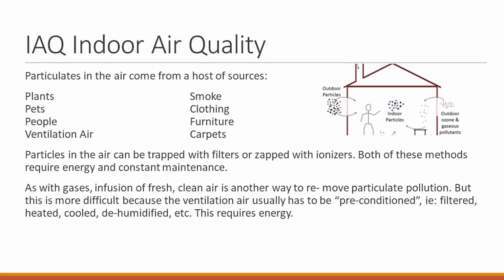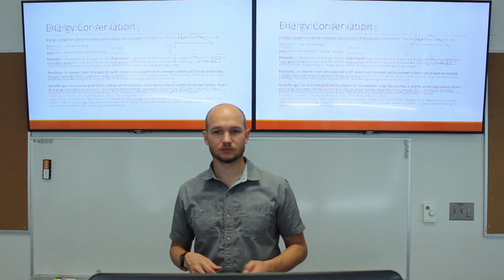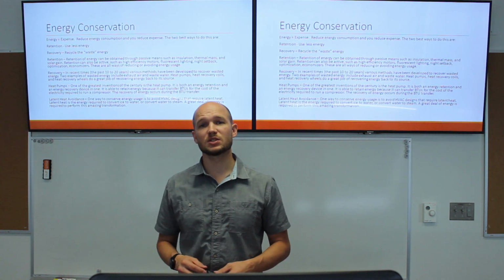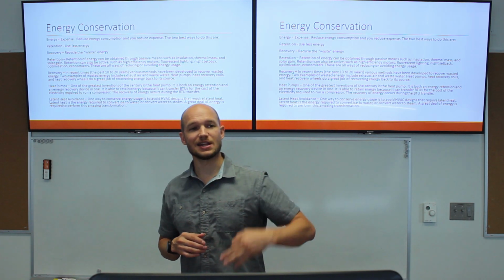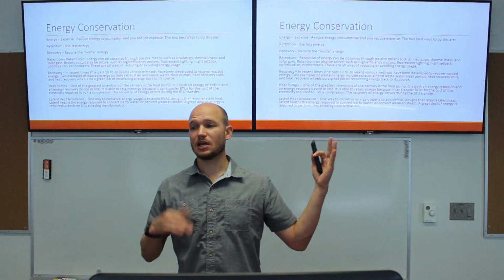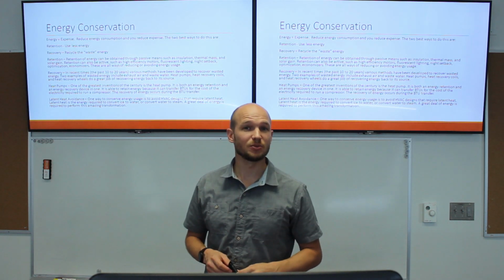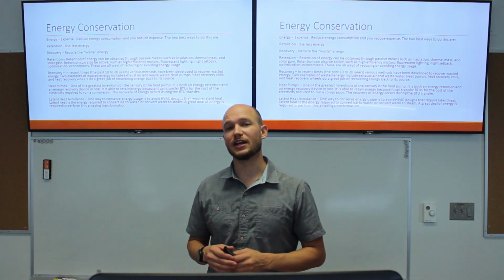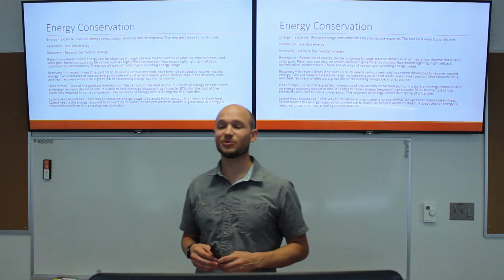So we talked about this already, but particles in the air can cause issues. So energy conservation, we can put in these systems and we can bring this outdoor air in, but what do you do when it's 98 degrees out, humid, and you're putting a building at 72 degrees with 53% humidity? You gotta constantly cool that air, and if you keep doing that over and over and over, your electric bill is going to be pretty large.